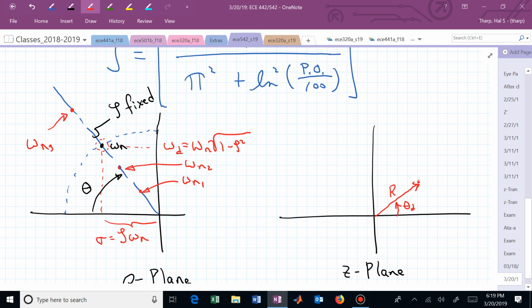Just the opposite, right? If we have 0 damping, what did I ask? Did I ask the wrong question? If zeta is 0, where are we in the complex plane relative to this first omega sub n curve? We're on the imaginary axis, right? We have no damping. All we're doing is shaking.